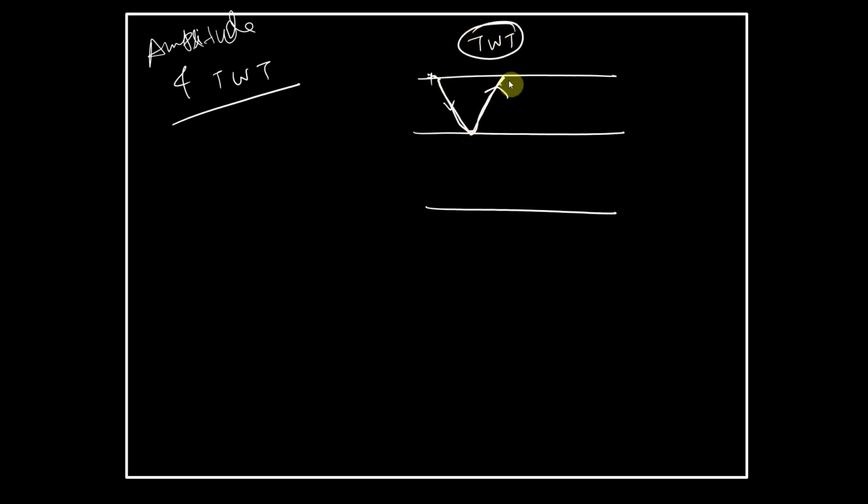The direction of the signal changes, the orientation or the path of propagation of the signal changes. So it's giving you the idea of two-way. So it's called the two-way travel time, the total time taken by this. And amplitude, you know, amplitude of any wave. So the amplitude will be recorded here, and the two-way travel time will give you the idea of the layer boundary. And how these layer boundaries are defined, I have already mentioned, is using the variation in the dielectric properties.